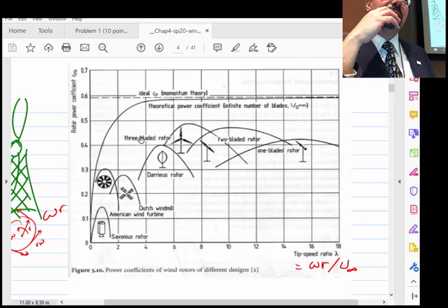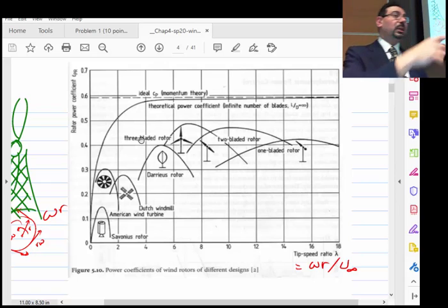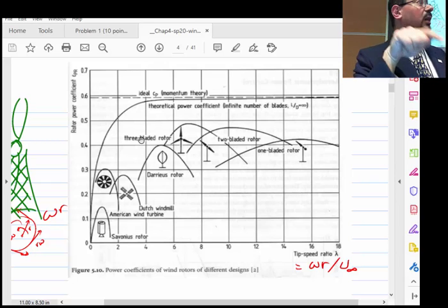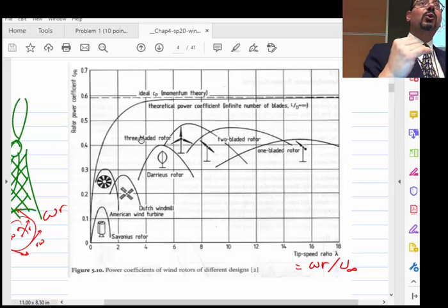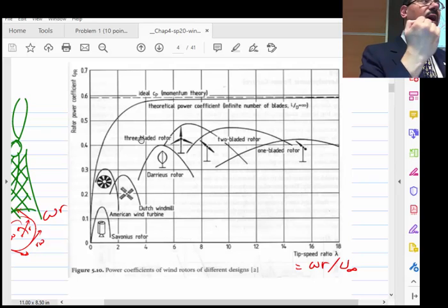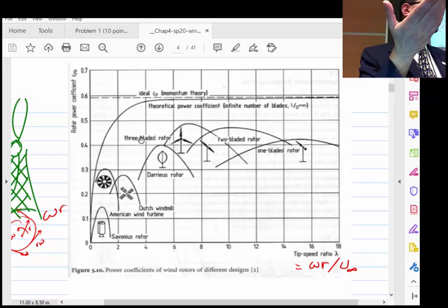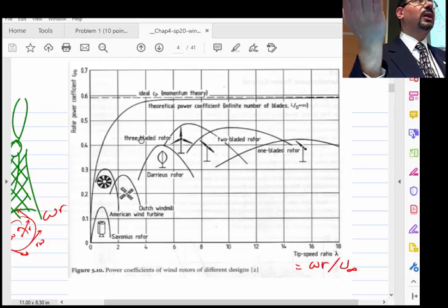No. So, I mean, Devin hit really the right place. Kinetic energy is not extracted to the fullest, because if we do, the flow will not leave. He's right, but why would the hydraulic turbine manage to extract 100%? Doesn't the hydraulic turbine also have the same problem? They also, if we slow down to zero, will not leave.